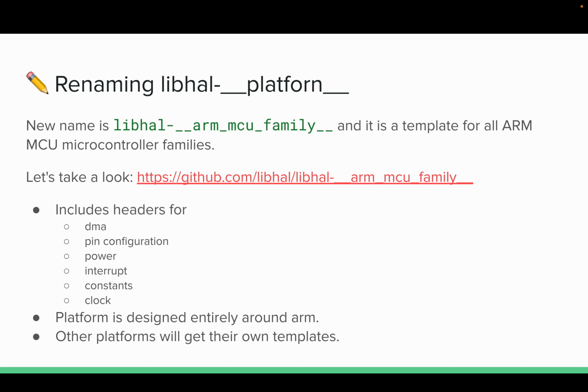Oh, and here we go. Here's the bring up guide. So let's go into the bring up guide. So for the bring up guide, we have to bring up ARM Cortex-M series microcontroller for libhal. There are several critical sections you need to do. So there are the Conan profiles, the linker scripts, the continuous integration, deployment, platform constants, and core APIs.